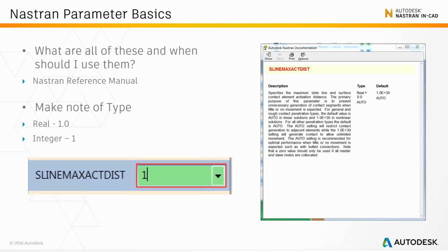But probably one of the easier ways, you can see that the box around our input area is actually shown in red, and it won't allow us to exit this environment until we've placed the right value in. So in this instance, if 1 is not the correct value, then you can try typing 1.0, which would be the correct value, and hopefully allow you to exit that dialog box.